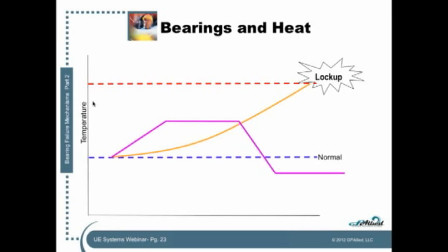And this confuses a lot of folks because their paradigm about bearing failures is that all bearings get hotter as they reach failure. Well, not necessarily true. All bearings get hotter as they reach a fatigue failure, or some bearings get hotter as they reach a fatigue failure. Most bearings don't lock up, they loosen up.